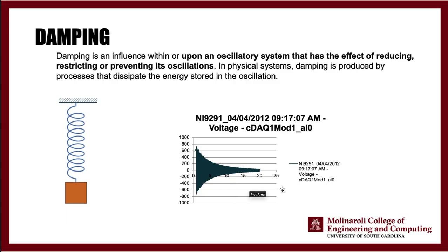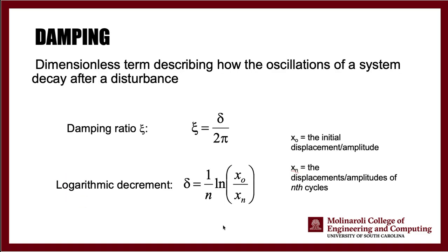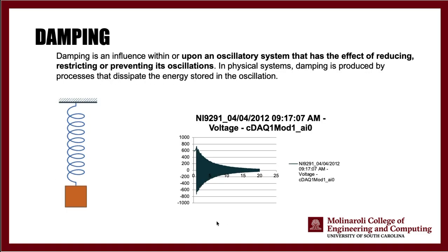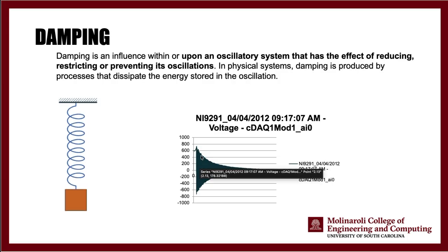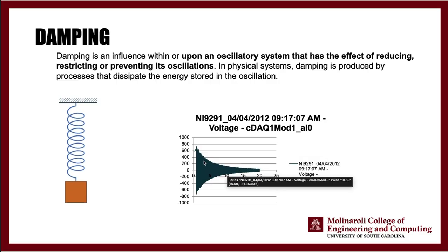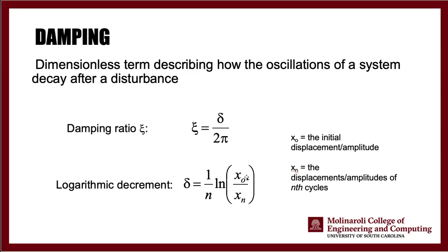And I have actually talked in detail about how to create a LabVIEW code to help you find this graph. Make sure you follow that lab recording as closely as possible, and create a good code that will help you have this graph. When you have this graph, again, this is a dying vibration, and you are going to take the first or second order, it doesn't really matter which one you take. You will take the first amplitude and the last one, or first amplitude or the 50th one, doesn't really matter. You should know the amplitude. You should put in here.